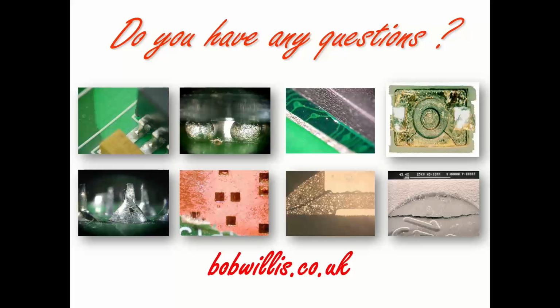But also think about alternatives. We talk about lead-free technology, but the advent and improvement of, and the move towards, low temperature solders is something that will benefit the industry in terms of warpage and damage to components and boards. So you're not just getting one benefit from that, you're getting multiple benefits. If your product is able to use those materials, which are becoming more popular now, that's something to investigate, because it does give you an advantage.